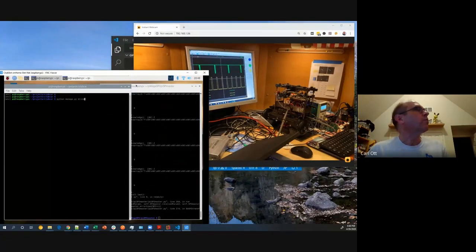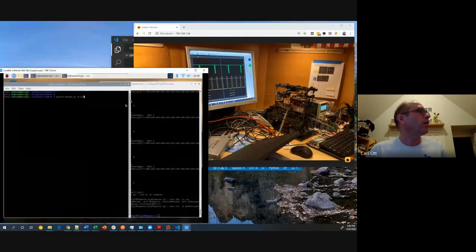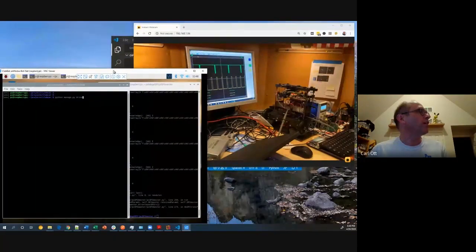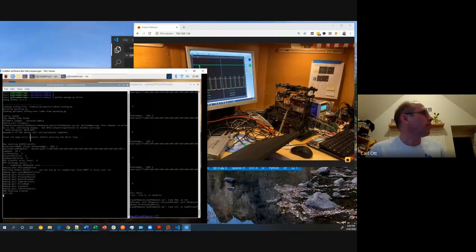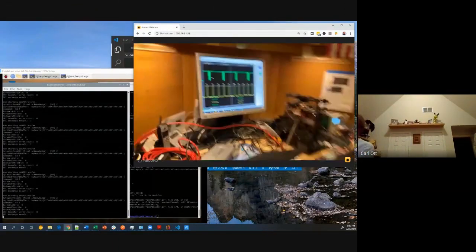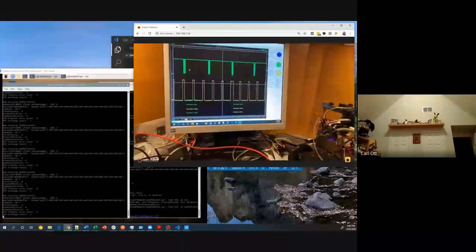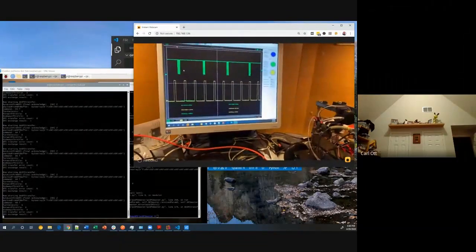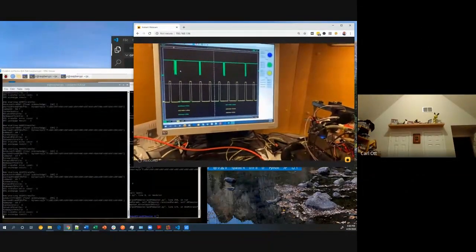What I managed to do was, I spent the weekend and read through all the donkey car software, figured out what it wanted, and made a part for my SPI interface. I embedded that part as a loopback mode into the donkey car. So now when I launch the donkey car software, you can see there's Donkey 3.1.2. It's adding all the different parts, including my interface. And now look at that. The Raspberry Pi is being a master again. If you look closely, with all the other junk going on in the donkey car software, the time interval between bursts on the Raspberry Pi side on top is varying around. And every now and then those pulses really stretch out.